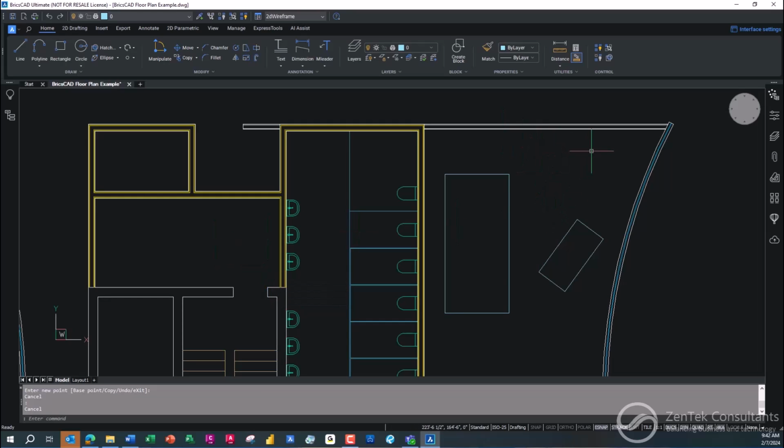I can also go in and when I've got pieces of equipment, I'm like, all right, what's the size of that piece of equipment? Maybe I need to make sure, maybe there are two models that are similar in size. I'm not quite sure which one they laid out. No problem. I can just select on it. And you see you get these green grips on the corners. If I just hover over one, you see it will actually give you the actual dimensions, or if you want to clean it up a little bit, you see that I can actually select on it. And see, I'm 5 6 3/4 by 11 10 1/2. I know the exact size that's been laid out. And it doesn't matter what angle it's on. I do the same thing over here. If I go to this one and pick on it, right, 5 7 1/4 by 2 foot 10. Simple, right? That's great. So I can get basic linear dimensions, measurements anytime I want.